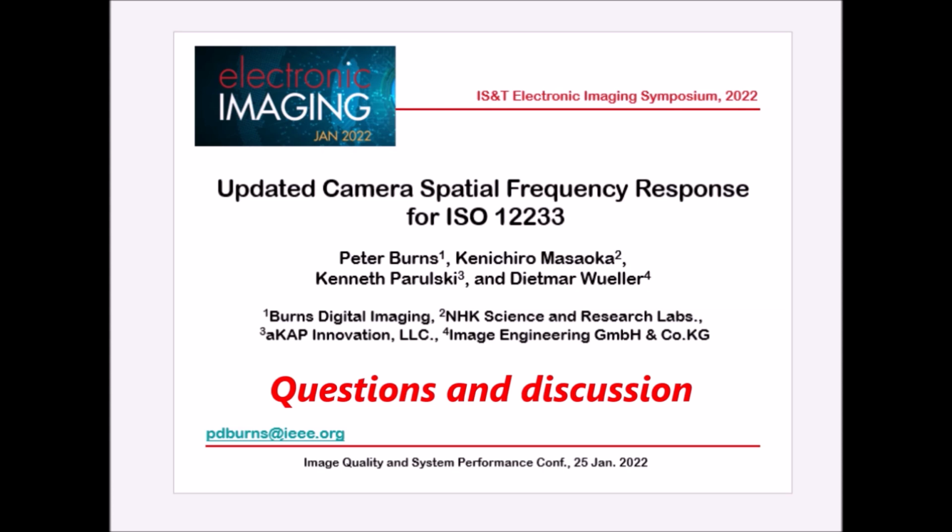Yeah, absolutely, you are. But I had the exact problem that I couldn't evaluate my camera in the mode it would be used on the road, because of the knee point. The knee point in the transfer function is where you go from, say, single-digit steps in the noise to 64 steps in the noise to 1024 steps in the noise.